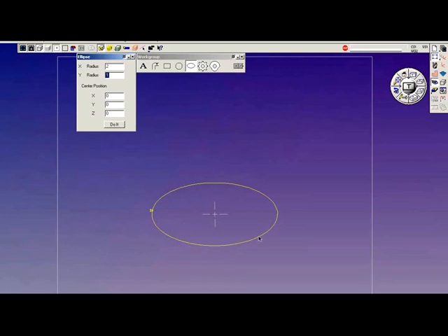This shape is defined by a series of short, straight lines. Okay? In the case where I want to machine this shape and minimize the amount of code that I get, because a B-spline will generate a large amount of moves, or G-code. It'll be a series of XY moves all the way around.